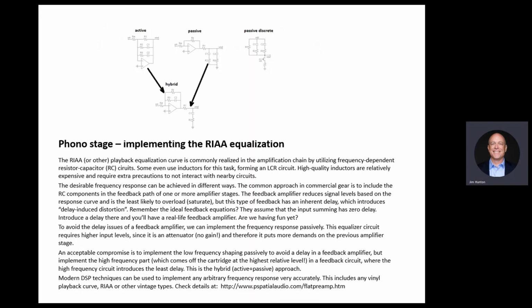Do you have a personal feeling about which is better? Personally, I like the passive. I think it's easier to design amplifier stages. In some cases, I will tolerate a hybrid where you have a simple low pass in the first stage. You cut down the noise that way a little bit. That's acceptable.